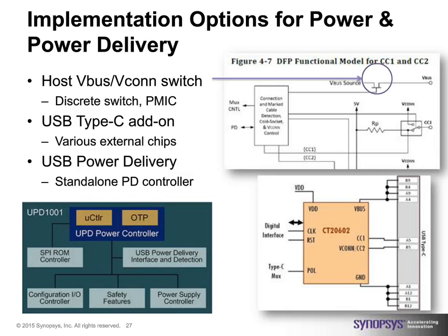There is definitely no one-size-fits-all for Type-C. There are also power delivery controllers available, standalone controllers that will do the power delivery communication that's needed for on-the-go, that's needed for alternate modes, that's needed for doing actual power delivery itself. So the sweet spot with regards to what's the best implementation, that will vary from one product to another.